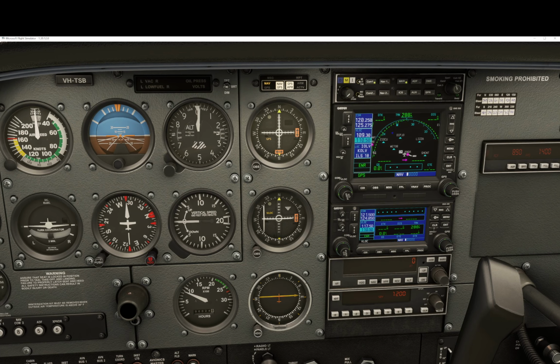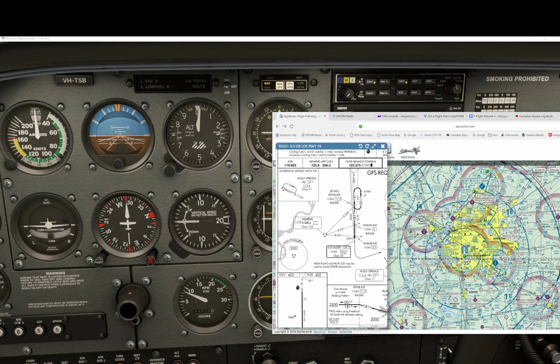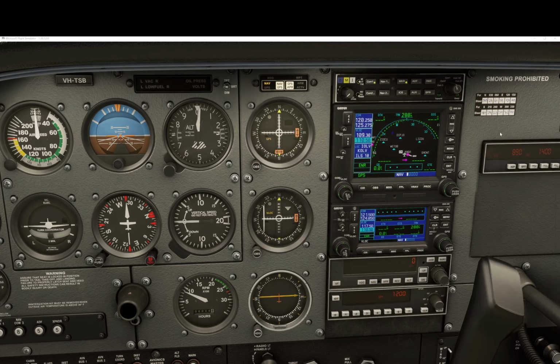Looks like right now, from Memphis, just to see if that's close or not. From Memphis we're going to be, Memphis VOR 117.5, and we're going to be somewhere up around 360 right now, so we can check and see if we're tuned to that. Even though it's not alive. Yeah, it's alive. So that's pretty close to what it should be.